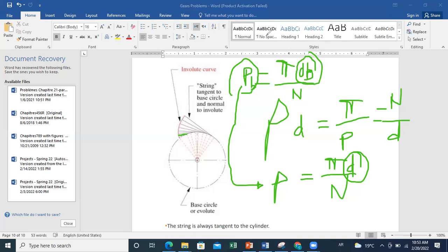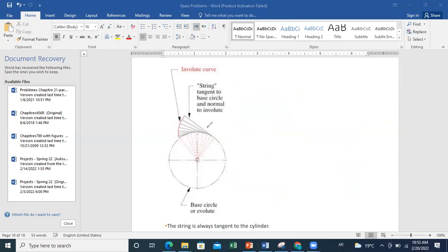So in the real case, how we manufacture it: I have the value of the base circle radius, and I want the involute. The teeth in reality will not stop here, because you have a form like this, and then you have a certain shape after that will connect it to the bottom circle. There is a difference between the bottom circle and the base circle. So if I give you a certain graph, the involute profile will not start from the bottom.